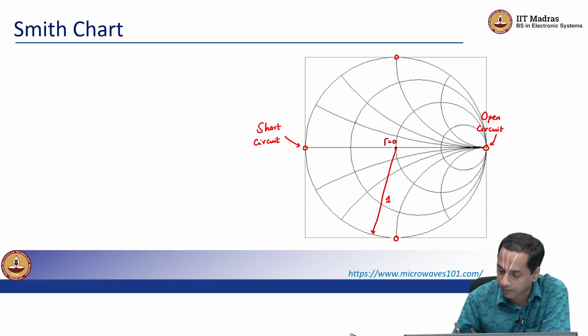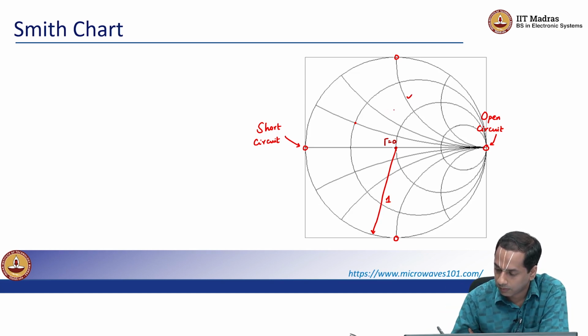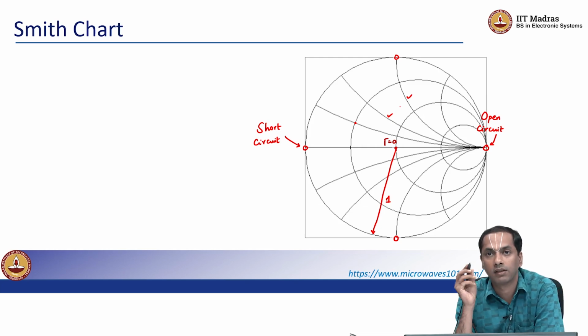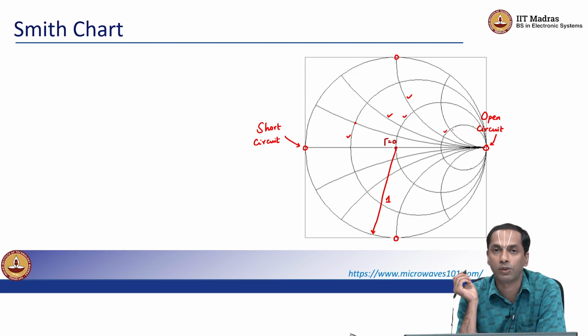And so basically if I have an intersection, remember these lines that are being drawn are essentially lines that have constant values of x, right? The ones that I have marked with the tick are essentially lines that will look perfectly straight in the z plane. So they have constant x values, or imaginary parts of the impedance, and these circles that you see, not quite concentric but reducing in radius, those are all constant resistance circles, right?